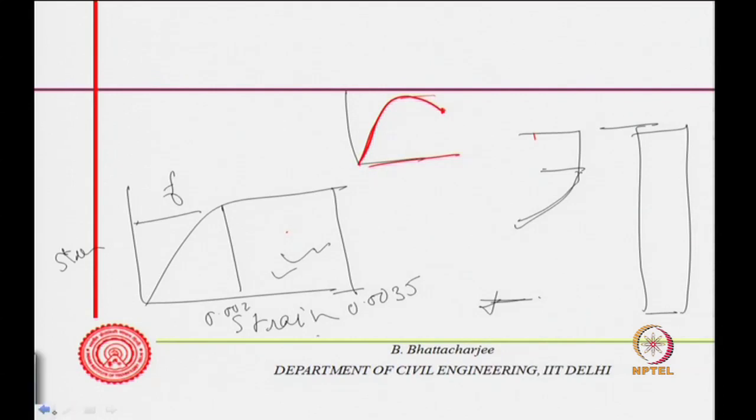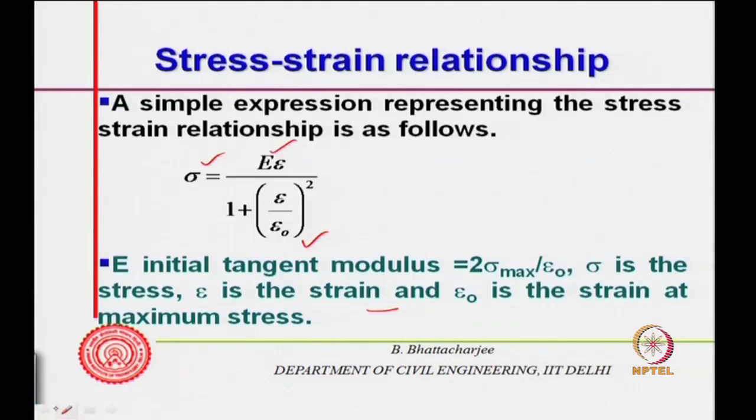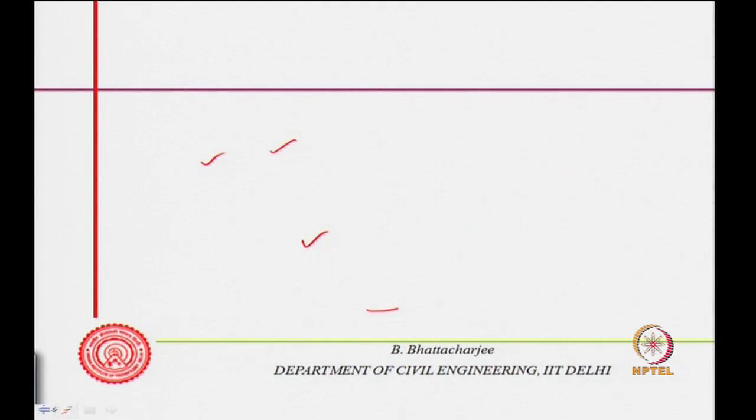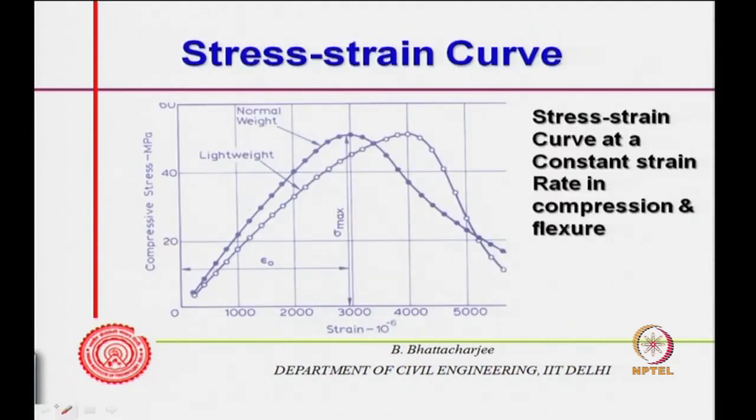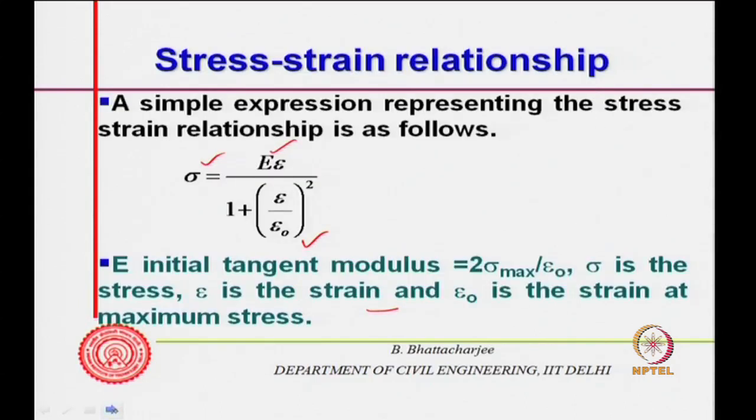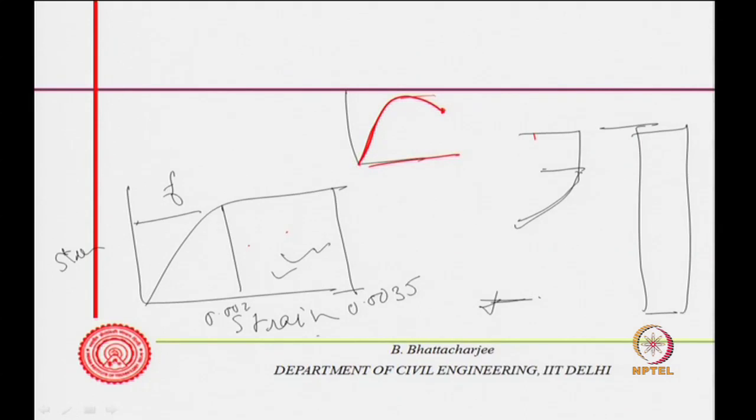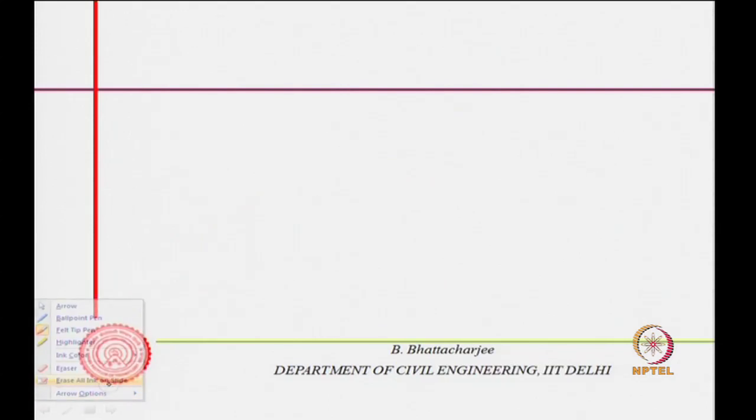The measured, actual stress strain curve that we have seen is idealized into this sort of curve, and of course, certain factors are applied to bring down the load as well, which I am not discussing at the moment. The importance of the stress strain curve is here, because in flexural design you have to use this. The idealized curve is arrived at from this real behavior.